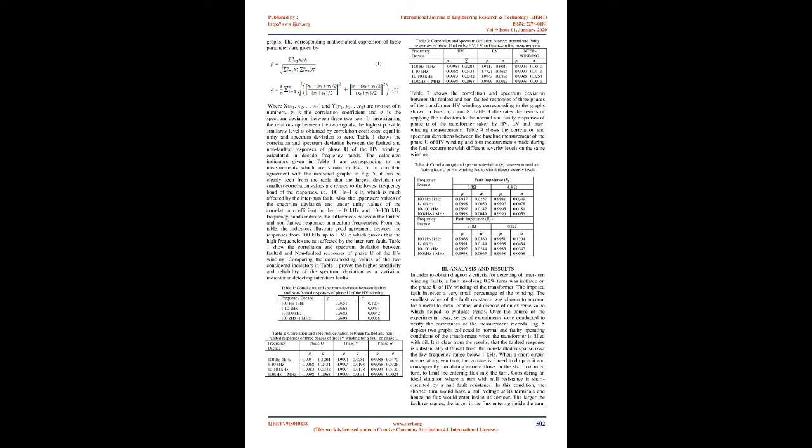Efforts were made by the authors in order to identify the most appropriate configuration for making sensitive frequency response measurements. Two different transfer functions, various terminal configurations and three categories of measurement types were studied. The sensitivity of the two transfer functions, i.e. voltage gain and impedance, was investigated by analyzing the frequency responses determined by each of the methods.